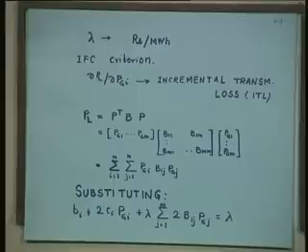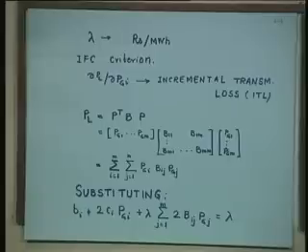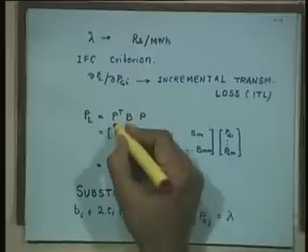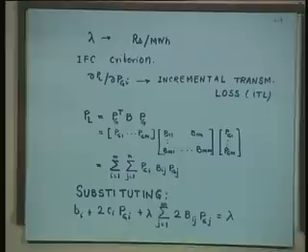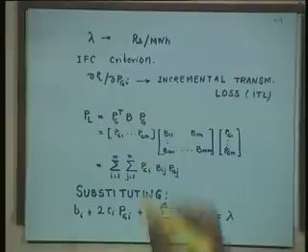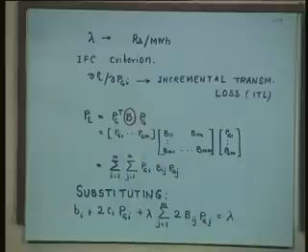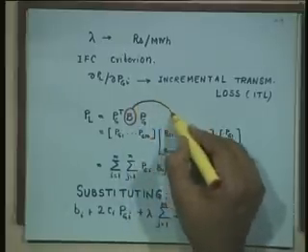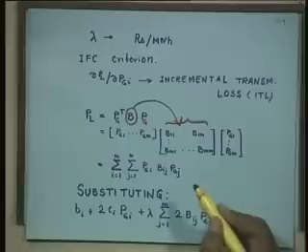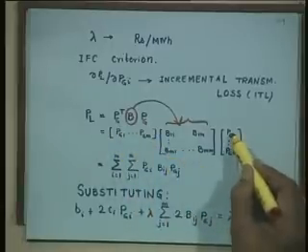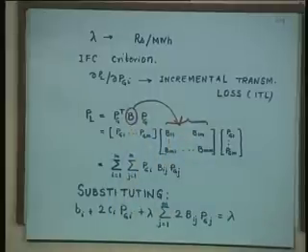Now the time has come to give you the expression for PL. We have talked about it a little while ago, but we haven't yet advanced any expression. Now I am writing an expression in three different forms. The first form is a matrix form: P transpose B P. P is a vector of power generation, if you want, you can even write PG. B is the loss formula coefficient matrix, which is given here in expanded form, PG1 up to PGM, and this is a quadratic form.